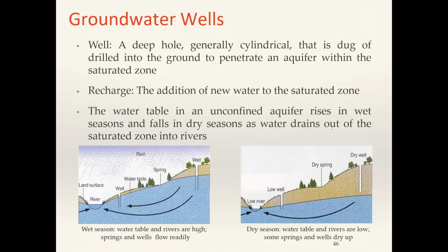For example, if you go to the Jaffna or the Kilinochchi area, especially the Kilinochchi area, you know that it is a karst aquifer. Therefore, the water level in the Iranamadu reservoir is directly connected with the groundwater aquifer. So the water level is sensitive to the water level in the Iranamadu reservoir. So the water levels in unconfined aquifers can be connected to a surface water body, and are therefore sensitive to the water level variations in surface water bodies.